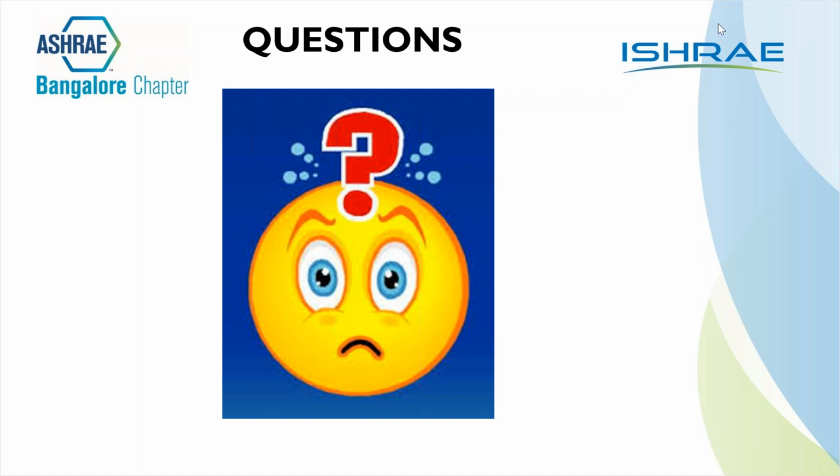Next question is, similarly even in VRF. What ADP do we need to consider for selection of VRF indoor units? Again, brand specific, sir. Some brands offer you 52 Fahrenheit, some brands offer you 54 Fahrenheit. It also depends on your design conditions. You need to manipulate your design condition based on the ADP of the coil of the manufacturer. If I design at 50 degree ADP and make a heat load estimate, and I cannot get a cooling coil that gives me 50 degree ADP, then I am in trouble.